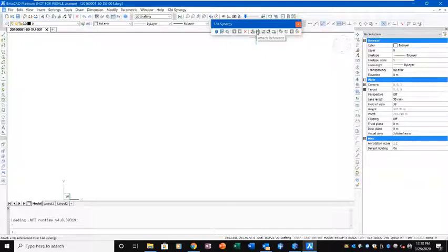This will synergize the paths for your XREFs and blocks. Basically, Synergy paths are unbreakable. So it doesn't matter if you rename an XREF or move the folder of Xrefs or the XREF itself, Synergy will track those movements and your drawings won't break, unlike a normal Windows Explorer path.